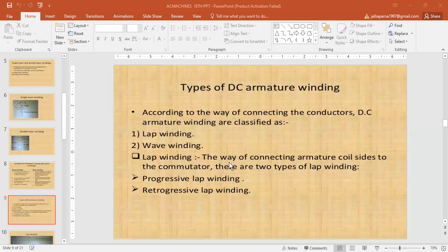The front pitch and the back pitch are each approximately equal to the pole pitch. That is, the winding should be full pitch. This results in increased EMF around the coil. For special purposes, fractional pitch windings are deliberately used. Both pitches should be odd,